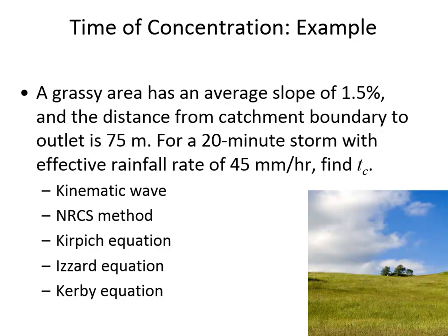And so you're going to see the same thing in estimating the time of concentration for the parking lot here next to the engineering building, that you get a wide variety of answers. Because you're making some assumptions for what the n value should be or what the flow path route is and therefore what the length is, I'm sure as each of you work, you're going to get a slightly different answer, and that's okay. I don't expect everyone to turn in the same solution.